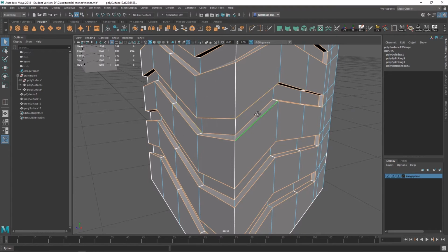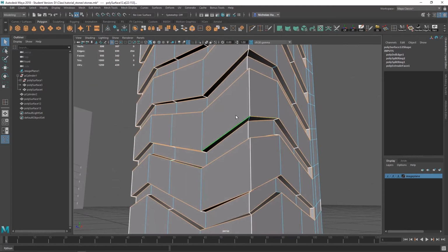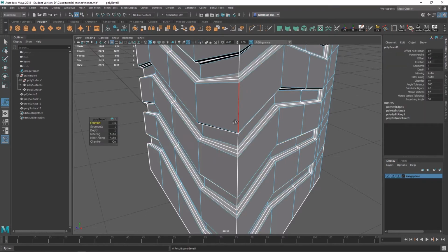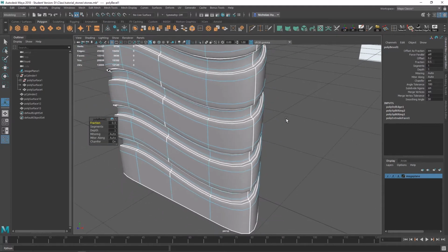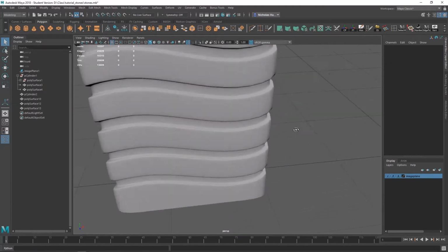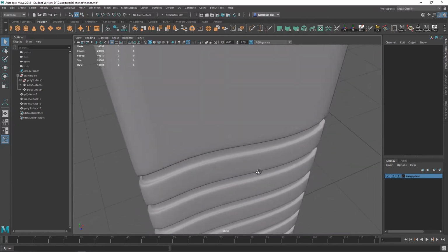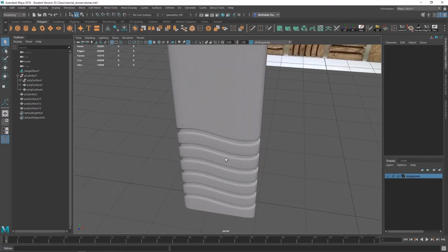Now we're going to bevel this, because ultimately when we bevel, we're adding edge loops to edges, and when we smooth, the closer edges are to other edges, the more that area is defined. So we're going to define these by adding a bevel to it. So bevel button is here, or if you want, shift, right click, bevel. And this might be fine just by default. I'm going to tap 3 to see. And then I'm also going to click off into space, go to object mode just to get rid of the selection, select off into space, just to see the shading. Really all I'm focusing on right now is the shape here. That's all right. It could probably be a little bit sharper.